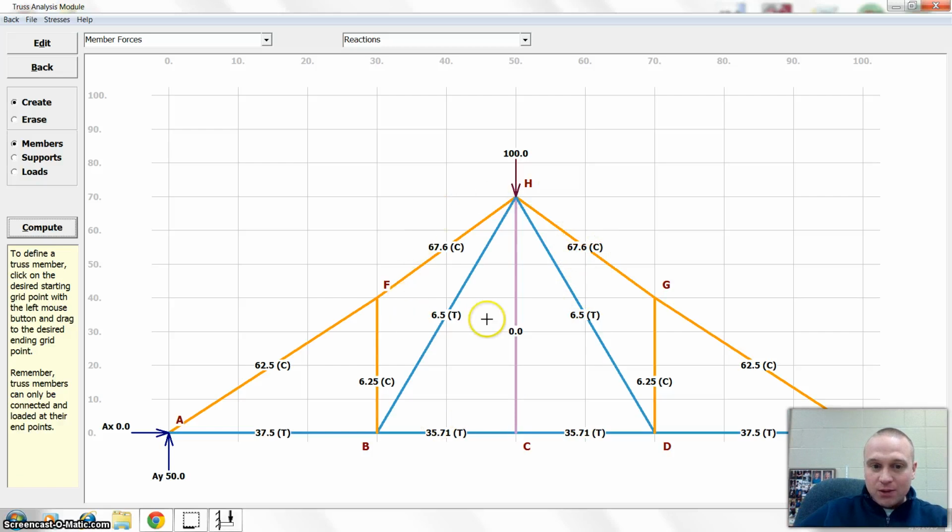And so if I wanted to make this truss better and more efficient, I would figure out how to make these members either have a larger cross-sectional area by increasing the moment of inertia, or making them shorter in length. So that's two ways that I could handle that buckling that's going to occur on either this member or this member.